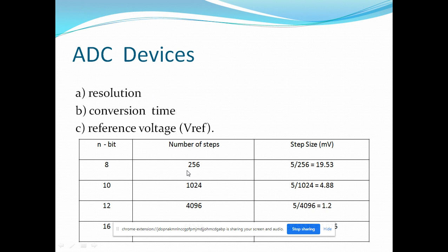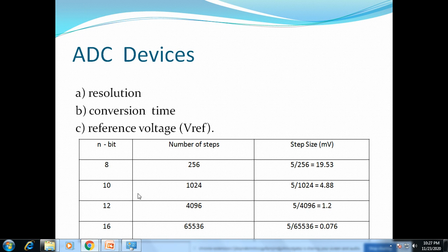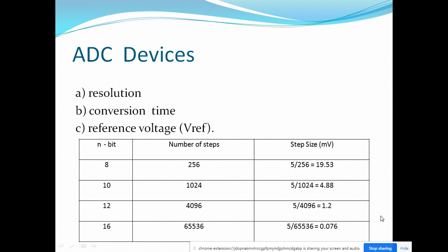But if we talk about the PIC18F4550, this particular Microchip device comes with an on-chip ADC. A 10-bit, 13-channel analog to digital converter is available on chip with this microcontroller. So 13 channels are there and your digital output is of 10 bits. So the resolution is higher as compared to 8-bit ADCs in the market. There are a number of types of ADCs with different bit resolutions available: 8-bit, 10-bit, 12-bit, 16-bit, 32-bit ADCs, which we can use for conversion of an analog quantity into discrete steps.